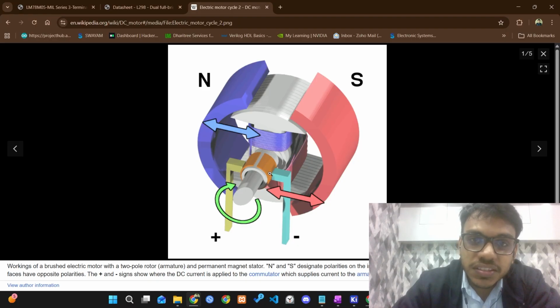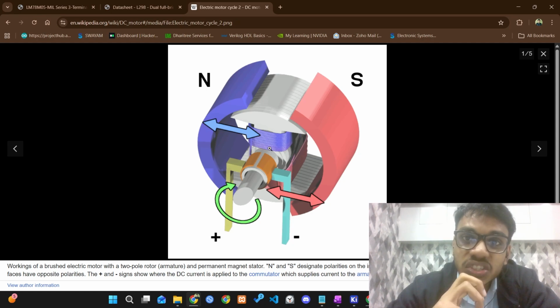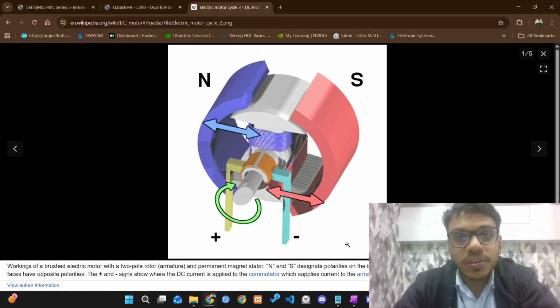Inside a DC motor, there is a coil of wires. Now, when you suddenly stop the motor driver, the motor actually acts as an inductor. So, as a property of inductor, it resists the sudden change of current. So, let's just see what happens when you suddenly stop your motor driver and why we need some diodes in our circuit.